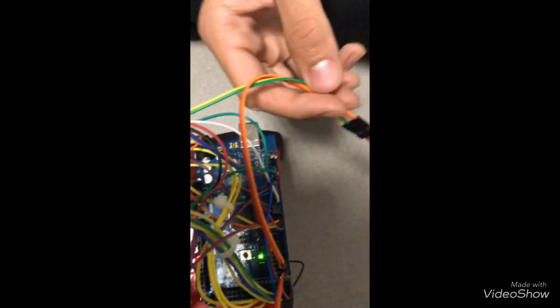Here are the 2 wires for trigger and echo, and 2 other wires for voltage and ground. I have 2 sensors, and we use a Bluetooth module HC06 to connect our mobile to the car and give it commands for forward, backward, right and left. And we use a buzzer here: if it detects an object, the buzzer will make a tune. Now we will look at the code.